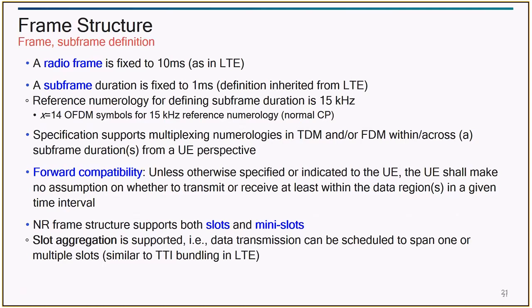You can do an entire transmission in a mini slot: downlink, uplink, ACK, everything. So, for example, if you want to go for an IoT sort of environment, then I can go with seven slots and give each slot to one UE.